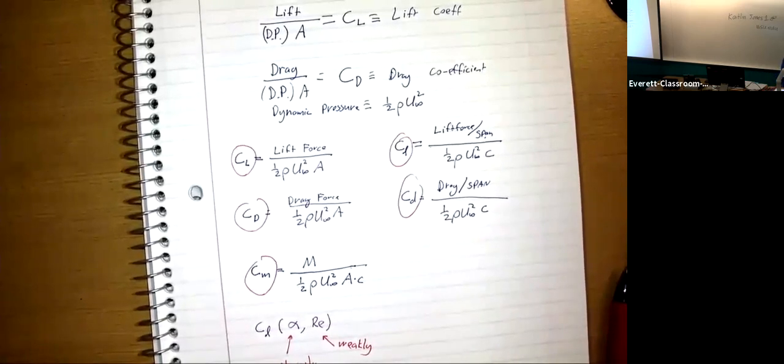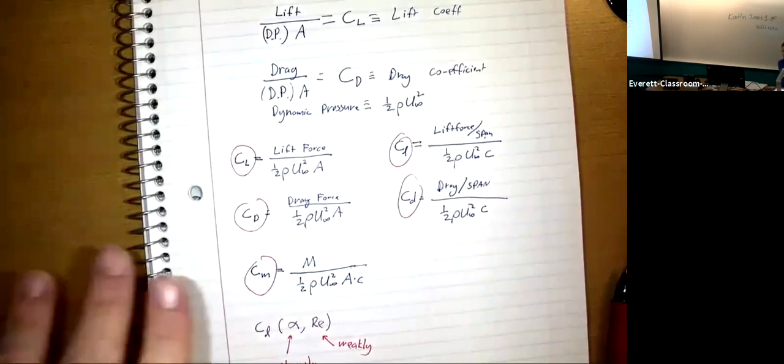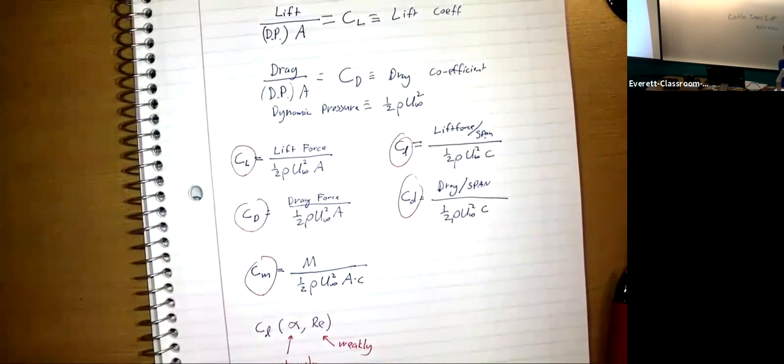So we can get a good approximation, a ballpark for a particular shape, of what the lift coefficient and drag coefficient are going to be, but you really want to do tests and experiments on that before you state it for sure. Luckily, there is an almost infinite number of airfoils that somebody has done an experiment on, and somebody has collected this data.